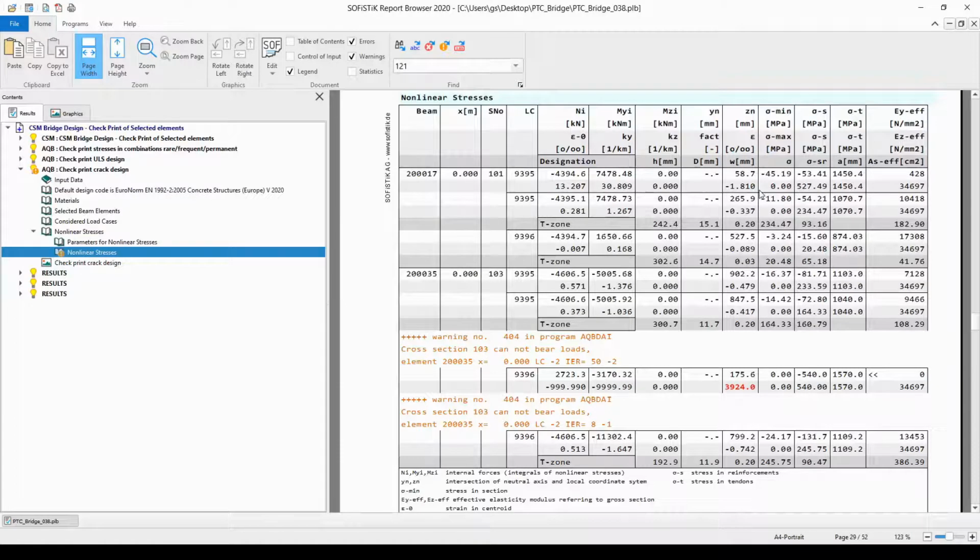If we cannot find a third line, it means that the crack width check was not satisfactory and the amount of the minimum reinforcement needs to be increased to fulfill the crack width criteria. And this is what we are going to find in the next three lines with the same load case number.